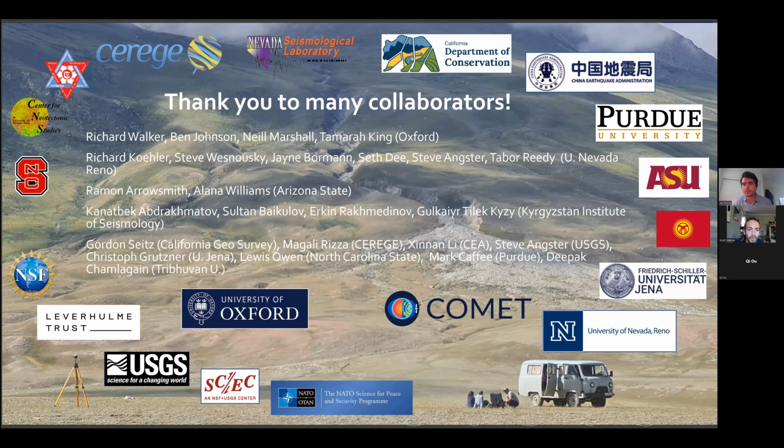I have a quick question to follow on from that. Some of your DEM profiles look very smooth. Do you have to do any filtering of vegetation or smaller scale features to remove their influence? In the Tien Shan, as you can see in the background of this picture, there's almost no vegetation, so they really are smooth. In a more vegetated area, that can be challenging. If you've got trees or farms, you have to smooth the bushes or trees out.